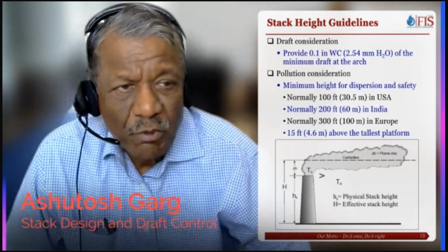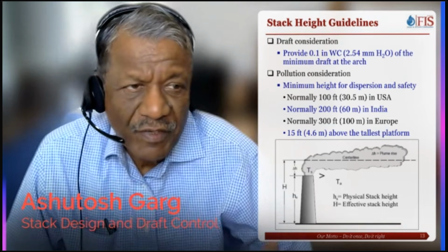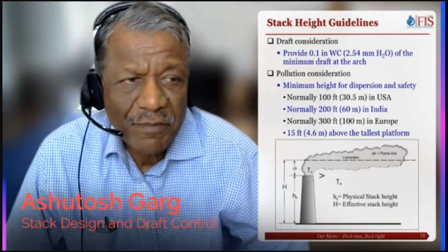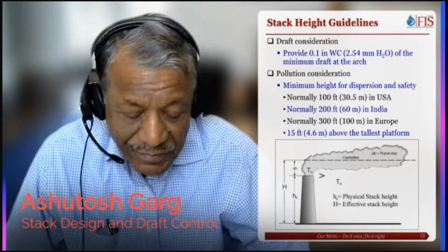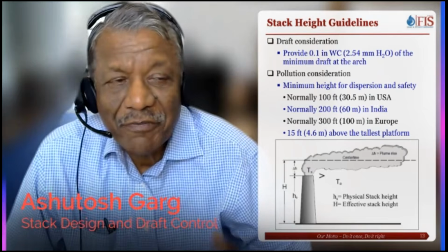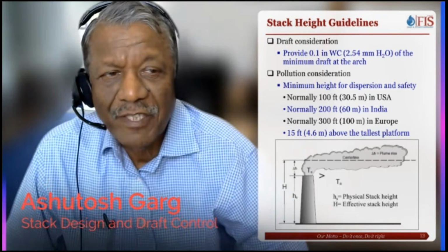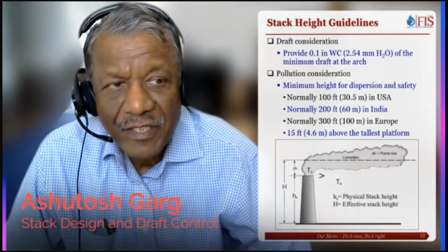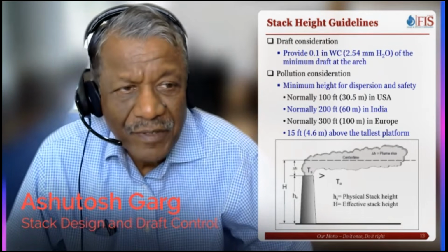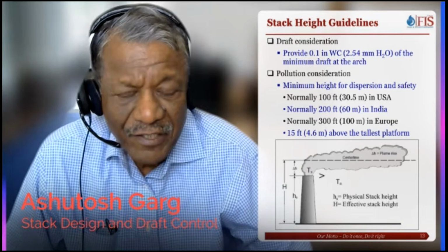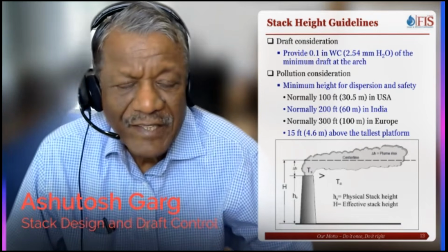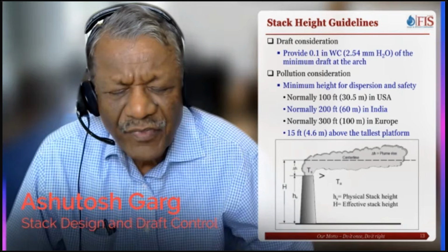Let's talk about pollution considerations. So we want to have minimum height for dispersion and safety. And here you will see very different standards in different parts of the world. In US, the typical standard is 100 feet or 30 meters. And that has been because of clean burning.